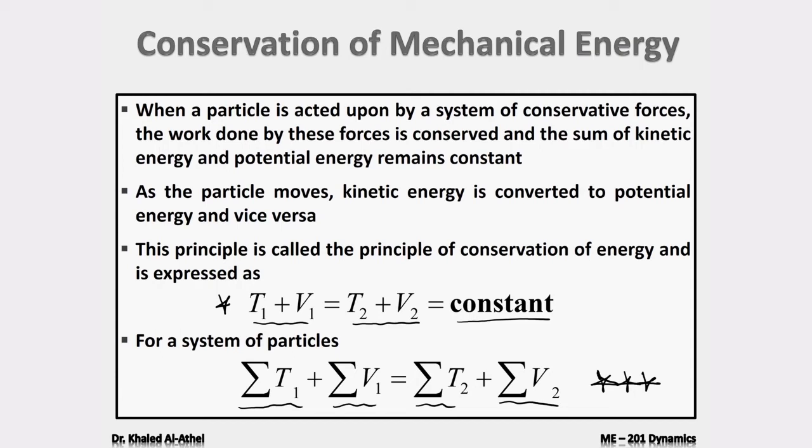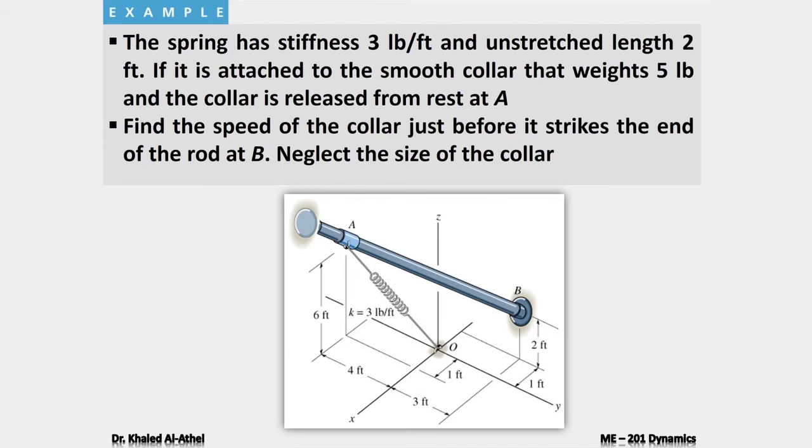And another thing that I need to mention: if you have only conservative forces, you can use this equation, or you can use the principle of work and energy. It's up to you. But if you have non-conservative forces, you have no option, and you have to use the principle of work and energy in that case. So let's start with the first example.